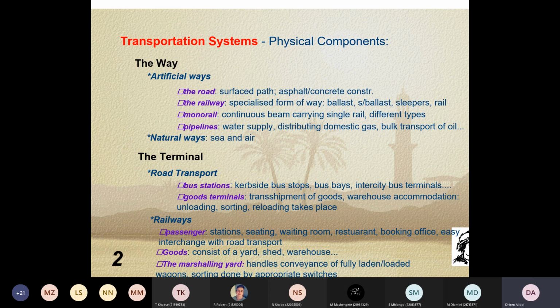So you have vehicles traveling on your road, it then passes these stresses onto your asphalt layer, which in turn passes it on to the base layer. The base layer reduces these stresses and then passes it on to the sub-base layer and so forth, right up to the selected subgrade layer.